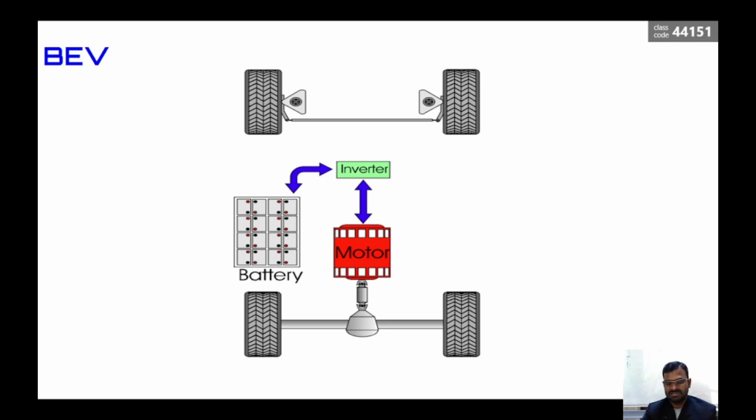The required voltages are maintained through this, and it is given to the AC motor, which may be either a permanent magnet motor or an induction motor. The motor converts that electrical energy into mechanical rotational energy, which is connected to the drive shaft, and the motor drives it, so the vehicle moves.